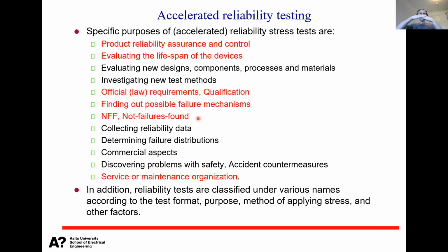So now the resistance is quite low, but then when you start vibrating it or you start heating it up, it bends and it opens. So locally the resistance is increased, and that's the reason that your customer said, okay, it's not operational.